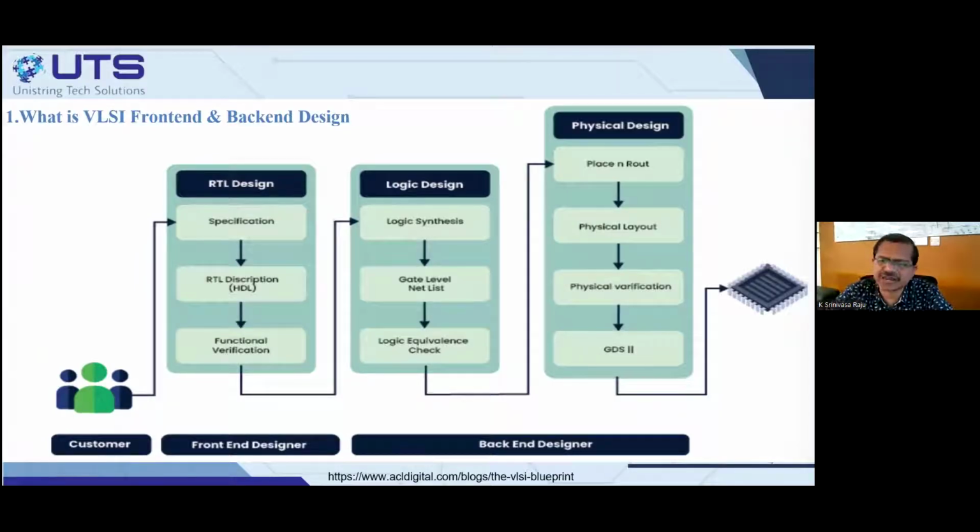There are ways to write VHDL and Verilog code also in a behavior style, putting a for loop inside, an if condition inside, a while loop inside, like that. But most of the time that is only simulatable. It is not synthesizable. Even if it is synthesized, its performance is not guaranteed to work. So RTL is a word.